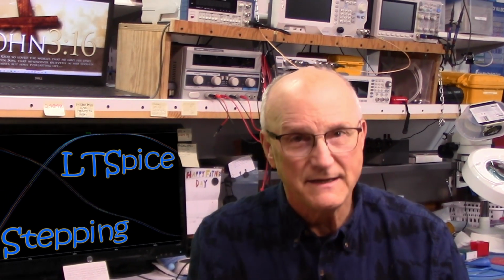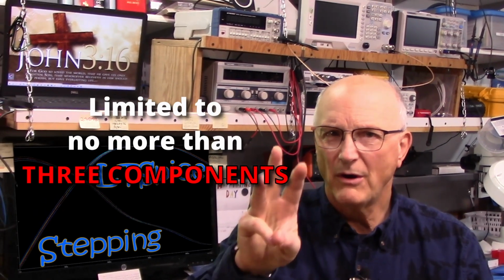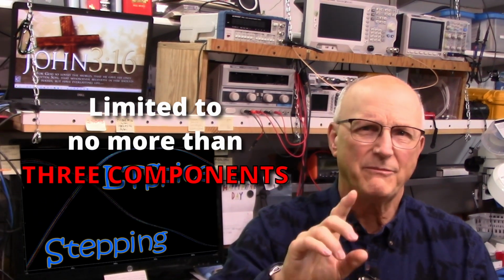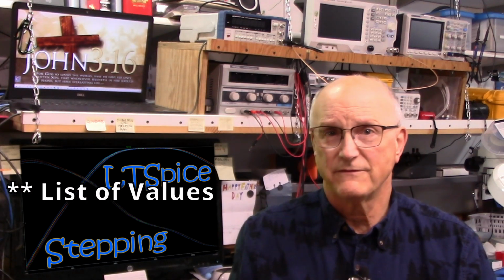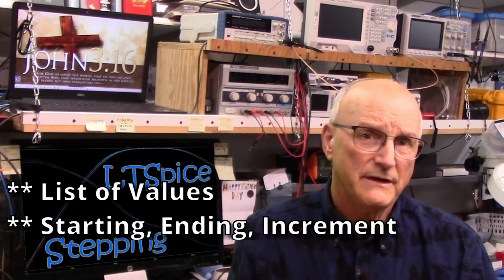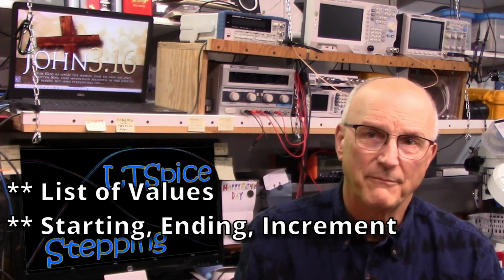So let's take a look at the easiest one first. Well, the quickest and easiest way to do this is using the .step command. Yes, this is the easiest, but it's limited to no more than 3 components. So you can step through values in various ways. You can provide your own list of values. You could give it a starting value and an ending value and a value to increment by.